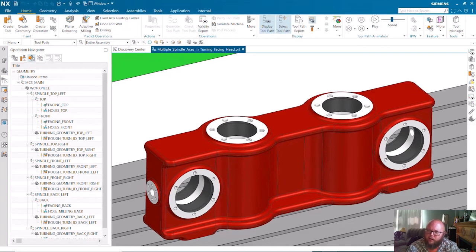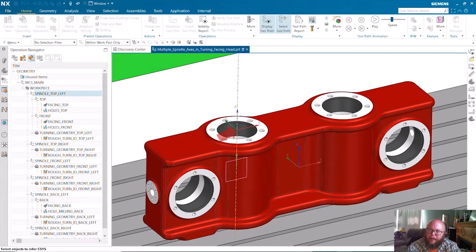And we're still programming our Z, our feed or depth of the operation, with our milling head, but the actual diameter of our feature is being controlled by this U axis, this auxiliary axis. So the big enhancement here is how our IPW is handled inside of NX with these multiple spindles, because we're creating different spindles for all the different orientations of our features. By default, in previous versions of NX, anytime we had a turning spindle, we would always want to revolve our IPW. Makes sense. Typically in a lathe operation, your part is spinning.